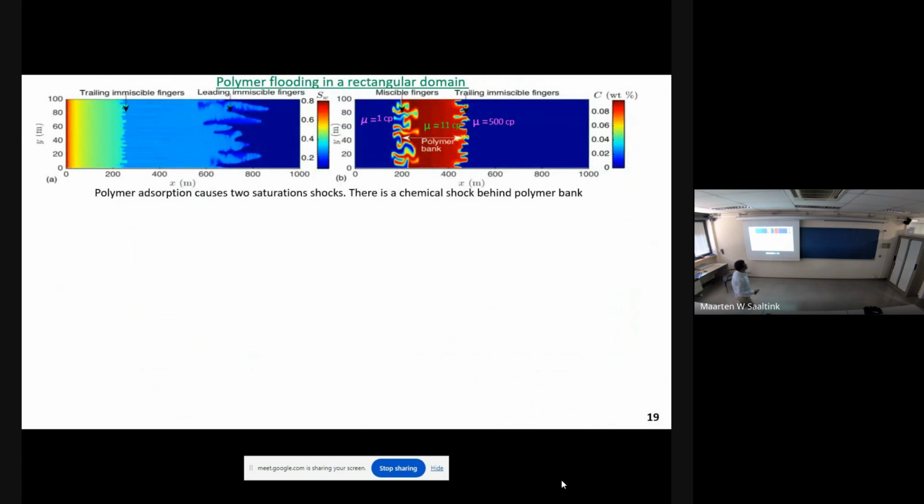One way of doing it is the grid sensitivity. If we see that they are not changing with different grids, then we can think of them as still physical. So there is a sort of convergence analysis involved before these numerical models. We didn't do anything very rigorous, but we do what we call grid sensitivity analysis, and then we concluded this is physical, it is no longer changing. Of course, if we have a very coarse grid, fine fingers will not be shown. But anyway, the fingers are quite thick compared to the individual grids.